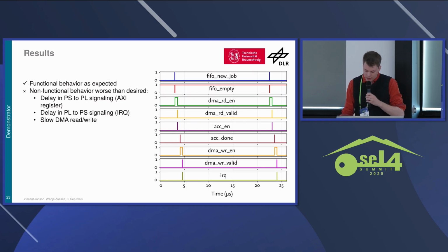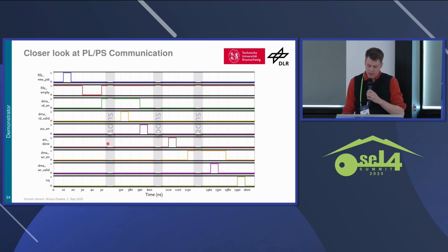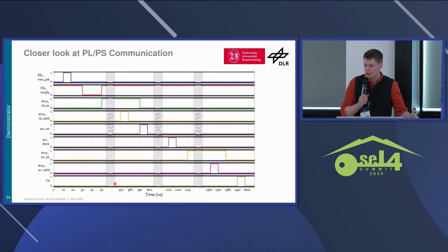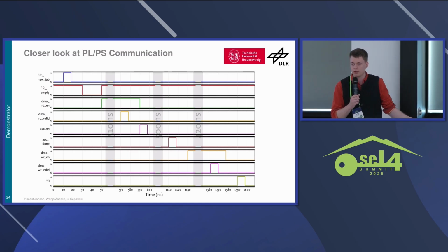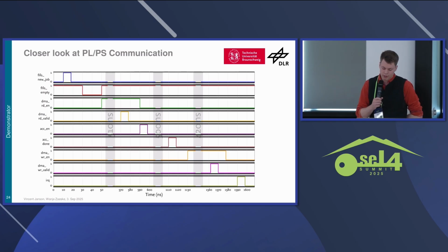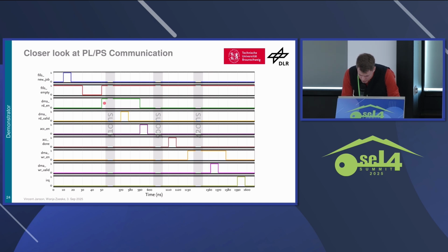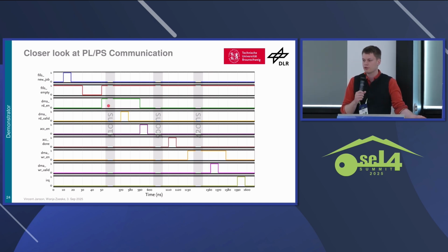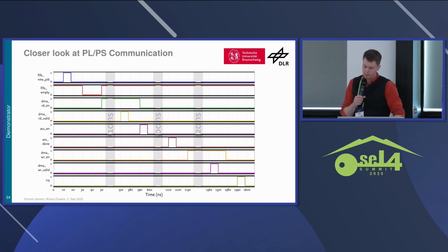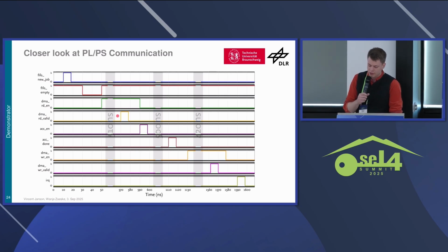I think we can take a rough look into the timing here. This is the timing of different signals of the FPGA. It's gathered using an external device, and so it's probably fine with regard to the resolution of time. We can see here in particular that the timing from the DMA read enable, so once the DMA controller is free to read data from the main memory of the processing system into the block RAM of the FPGA, took about 550 nanoseconds or so.